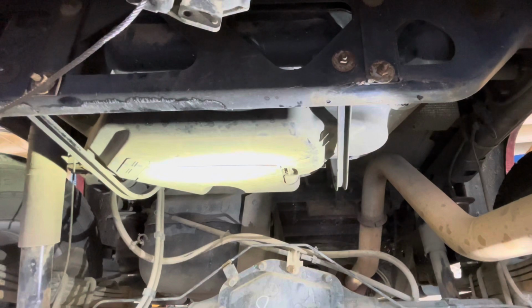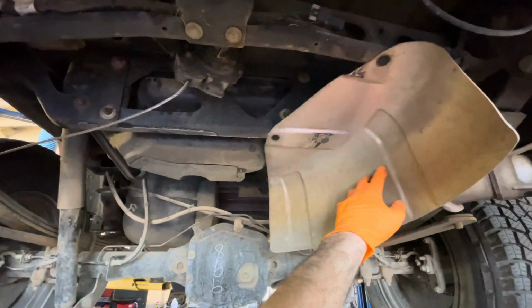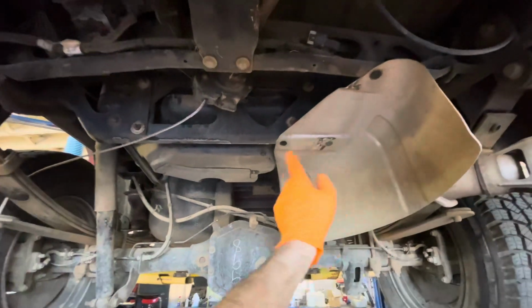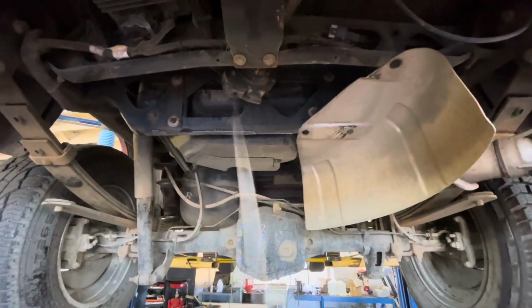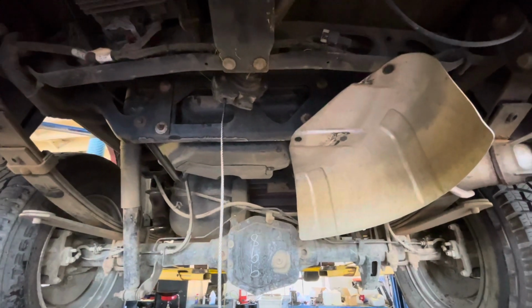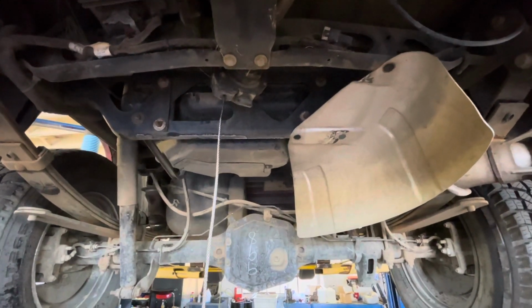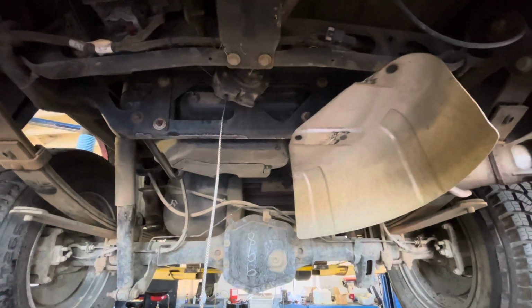Then from there you just reinstall the spare tire and that's it. Don't forget the spare tire heat shield also. So we're all reassembled. I just need to put this back in position so I can lift the spare tire back up and then put exhaust fluid back in, and we're going to do the reductant fluid pressure test, or the leak test.